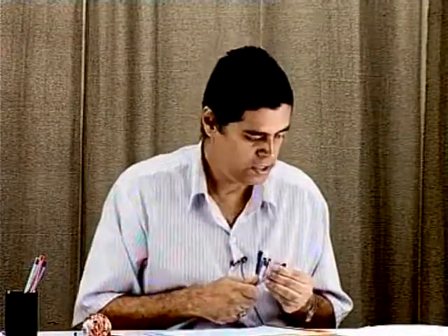But in the Gummel-Poon model, which will be coming later, after the mid-semester examination, you'll find drift is automatically incorporated. Here also, some attempts were made to incorporate drift and diffusion together in modeling the current. I will give you only some hints and tell you how there is some further improvement in the calculation.